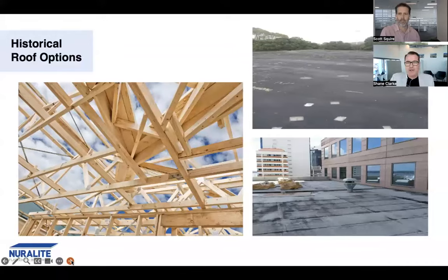Yep. So right up until 2008, it was permissible to use a single layer of membrane on plywood. Funnily enough, times have changed, and for the better. People are wanting higher performing roofs. We're wanting continuous insulation. We're wanting higher insulation. We're wanting more robust membrane systems.